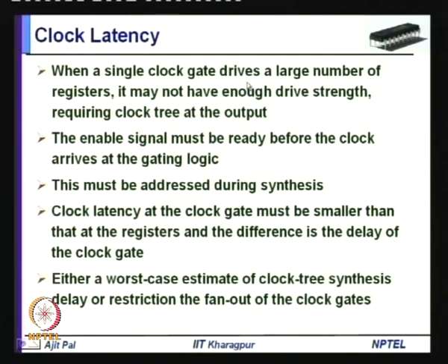So, when a single clock gate drives a large number of registers, it may not have enough drive strength. So, you will require a clock tree design. You have to design a clock tree, not a single clock which will drive the entire circuit. You have to use drivers, and a clock tree has to be designed. Clock tree design has become very important in present day digital circuits.